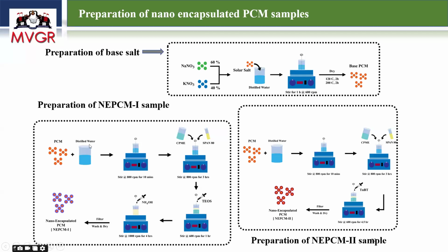The same procedure can be followed. Instead of the TEOS solution, we are using a TNBT solution, tetrabutyl titanate. If you do that stirring process, these bonds will automatically break, and only titanium oxide will be coated over the phase change material. So it is actually nano level synthesized.